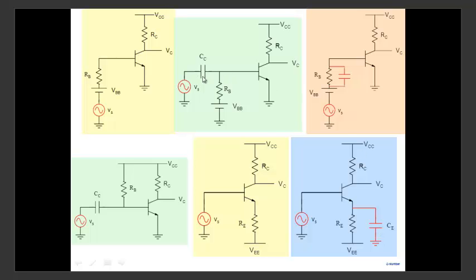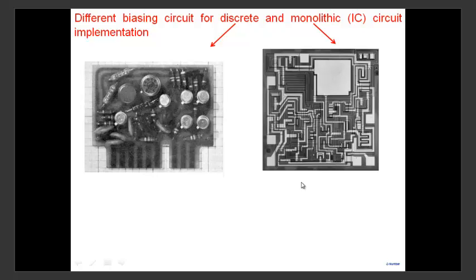Most of it is inside the chip, but remember, most amplifiers would be multi-stage. Multi-stage means one stage like this, and the output of this stage will be connected to the input of the second stage. So how would you connect? Well, you would require a capacitor here also to couple it to the next stage. So you're not just building one simple amplifier, one simple stage. You're building a multi-stage amplifier. So again, these kinds of things are not suitable for implementation on a piece of silicon.